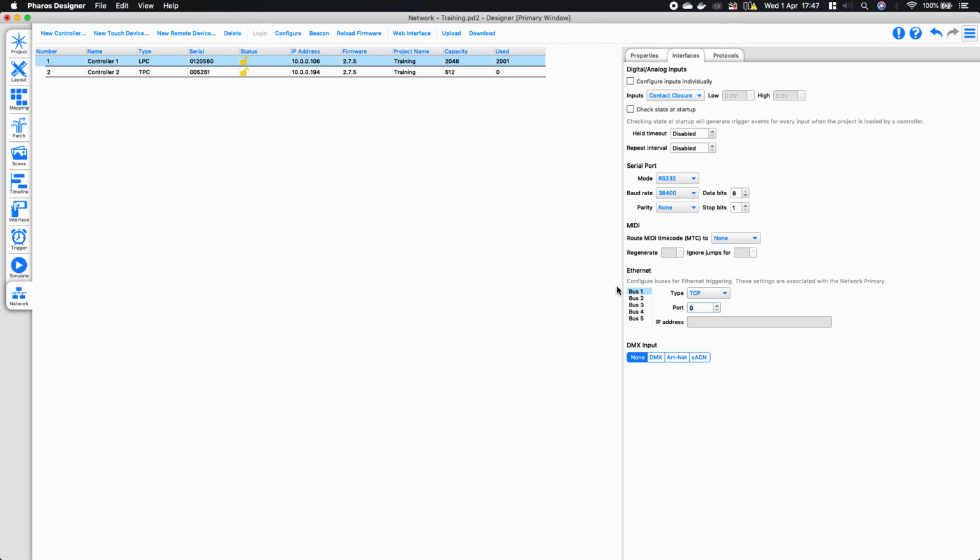And then what I'm going to need to do is open up a port on my controller. So generally speaking, it's recommended that you leave the first 1024 ports reserved within your system, as a lot of other protocols use those. So pick a port number that's a lot higher than that. A common port number to go to would be something like 8080. So essentially what that's going to do is open up that port on the controller so that it can receive those commands.